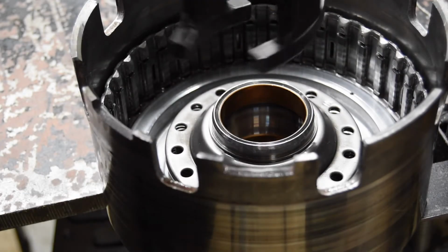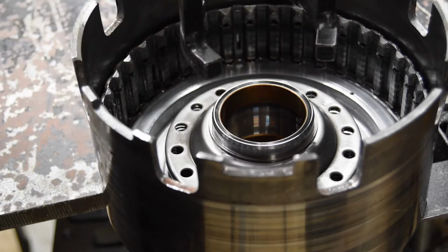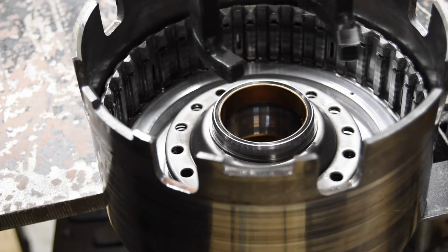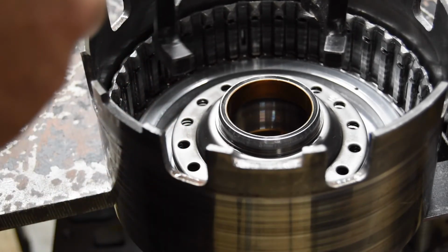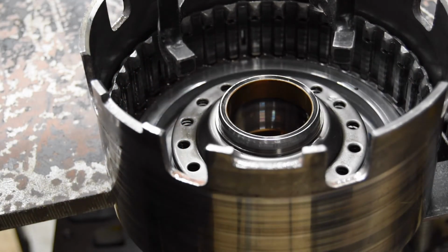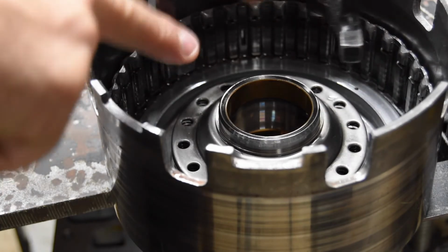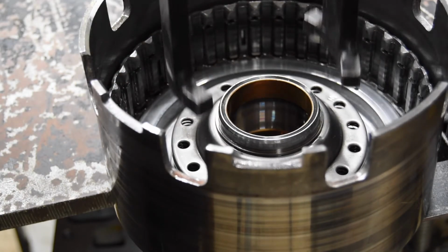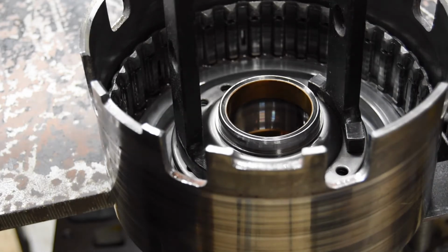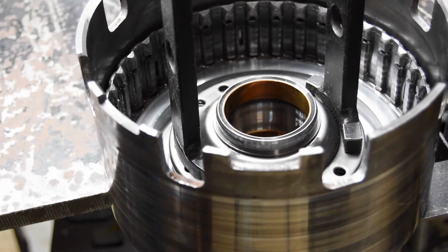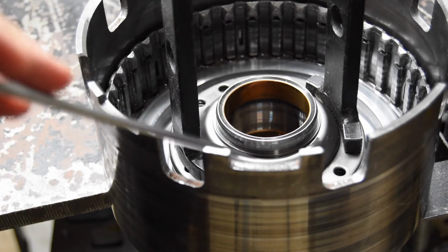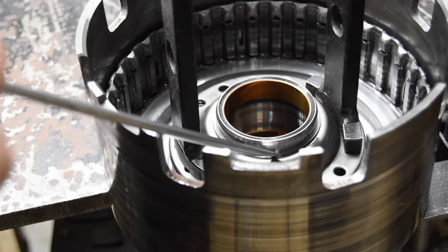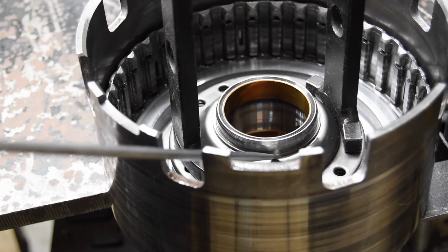All right, here we are over at the clutch return spring compressor. This is a table mounted model. You'll be using probably the free-handed model. And what I'm going to do is position these legs here down onto that return spring plate. So I'm going to drop that down inside there. I'll lock it, and I'm going to start to rotate. And if you watch this area right here, you see that area there? It's going to slowly lower down.